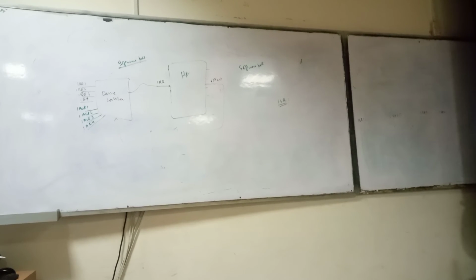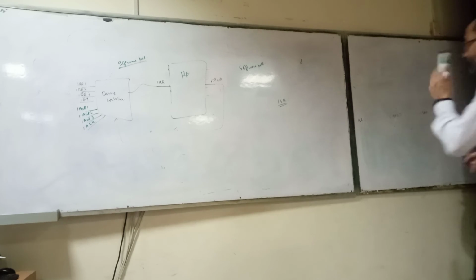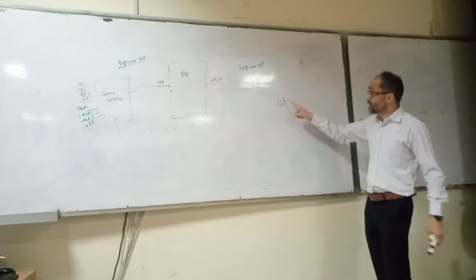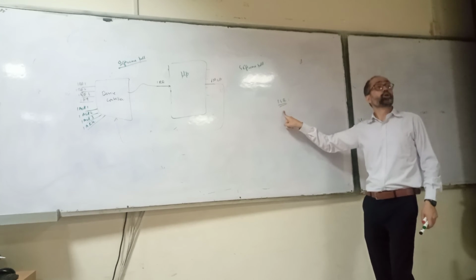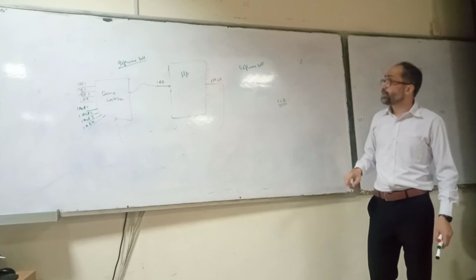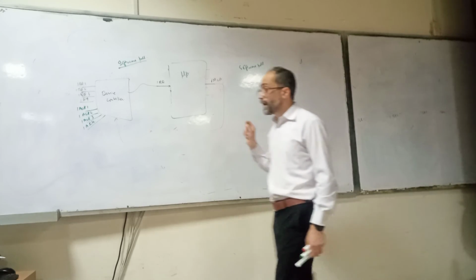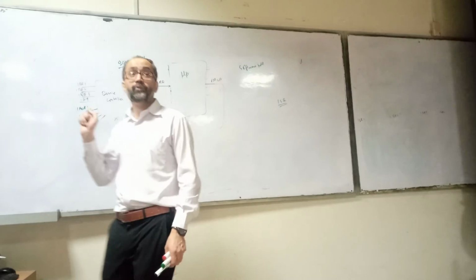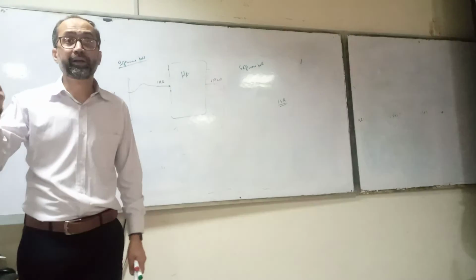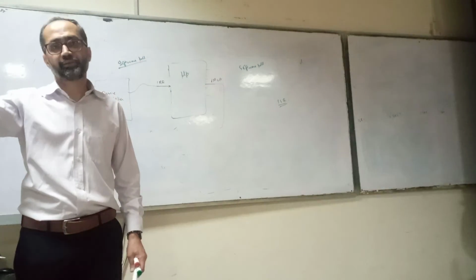Before jumping to the ISR, what will happen? The context will be stored. The context of the program should be pushed on the stack. So that will be done, and we are not going into those details. So in software polling, there is a general ISR that will be called for each of these interrupts. Then the microprocessor will ask each individual device to check whether it has generated an interrupt.